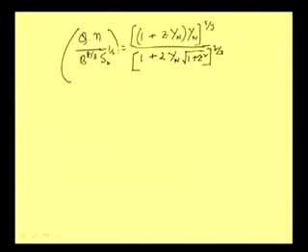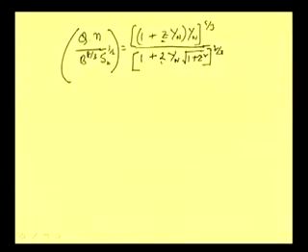Well, now when we are saying non-dimensional form, then what about this particular part? That we will have to be sure. Well, we are sure that z is a side slope, so it doesn't have any dimension. Then capital Y_n, that we already mentioned, is a non-dimensional depth. So Y_n divided by b, the normal depth divided by b, is also a non-dimensional parameter, so it doesn't have any dimension. And as such, this right hand side we are sure has no dimension, that is confirmed.